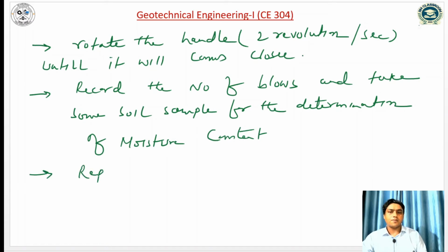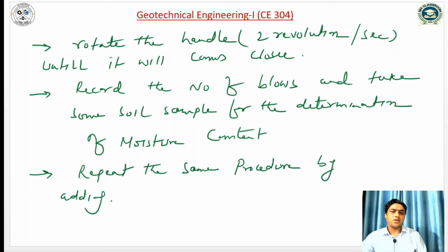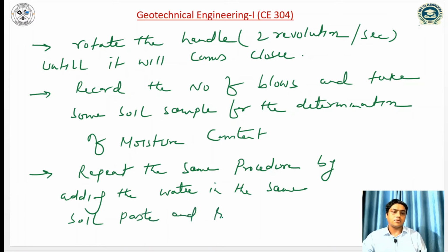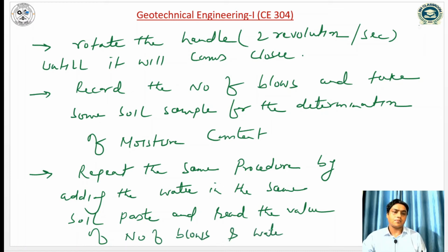Repeat the same procedure by adding water to the same soil paste, and read the value of the number of blows and water content.